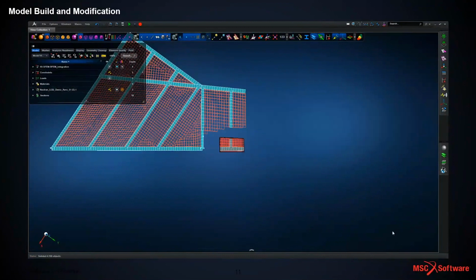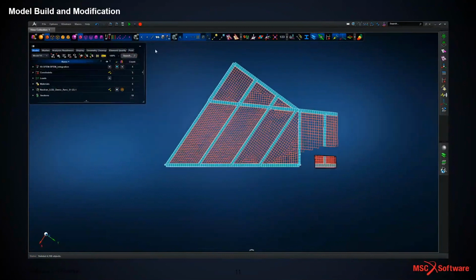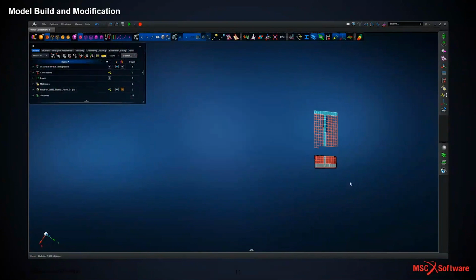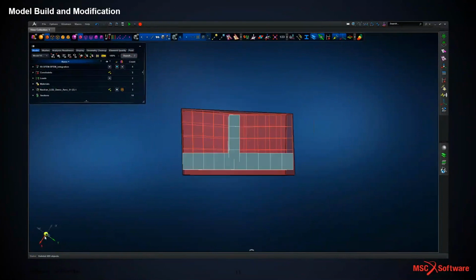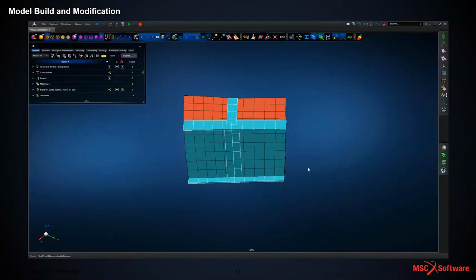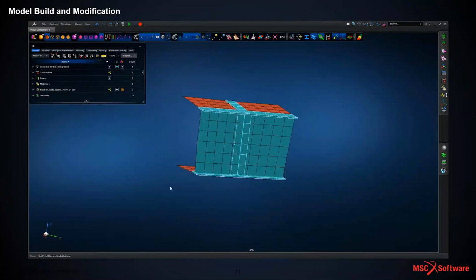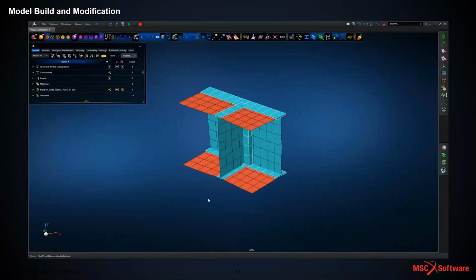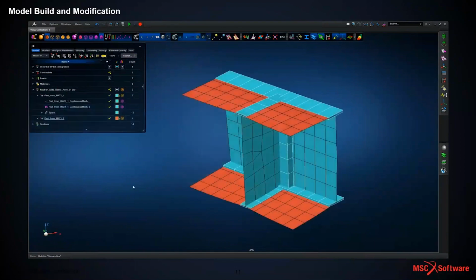What we're going to be looking at is a mesh to CAD type operation, which is the inverse of the way industry's been talking, which is CAD to mesh. Obviously with Apex we can go both ways, CAD to mesh and mesh to CAD. So just taking the volume out of view and looking in the model browser tree, we can see we've got 2 discrete sets of entities left, a wing box spar, a rib, and then a couple of wing skins, the upper and lower wing skins.